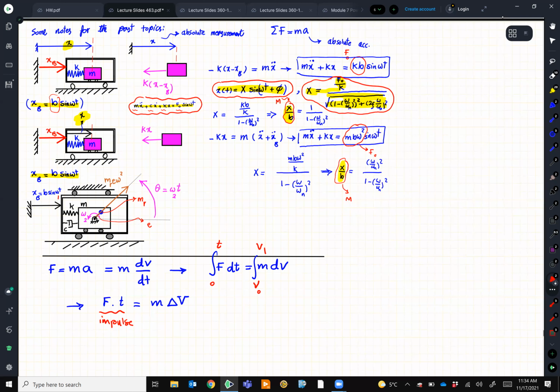They apply load on a mechanism, which we gave them. But one thing that was important is when you apply a load, let's say to crack a walnut, do you apply it all of a sudden in 2 seconds, or do you apply it slowly with that mechanism that we gave them? One thing that they had to calculate was the impulse, force multiplied by time. So always when you apply a force, it's important how long it takes to apply it. It gives us something which is mass multiplied by delta v, which we call linear momentum.